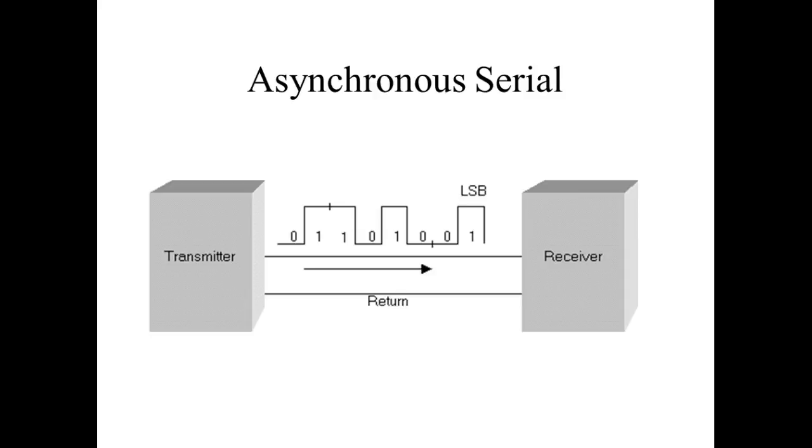If the transmitter and the receiver transmit and receive at exactly the same rate, then that would be like me and you. I've got a time on mine. I'm not beeping anymore, but what you've got is you're beeping in your head. Or you've got a watch or something. It has to be pretty precise, right? And I'm up here, and we're synchronized, and I'm sending out 1 bit per second. I change it up here, and you read it 1 bit per second, but I don't tell you when to read it. You are doing your own timing. And this is called asynchronous. Right off the bat, we save 1 wire.